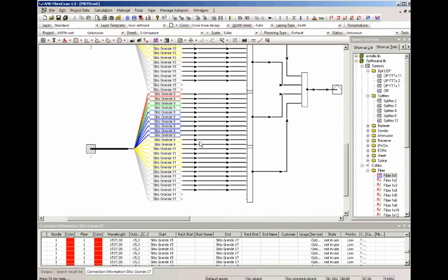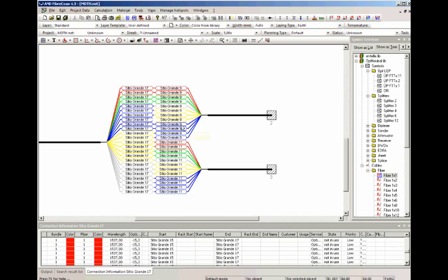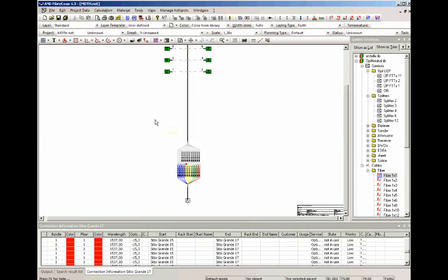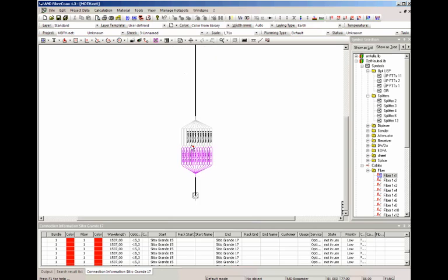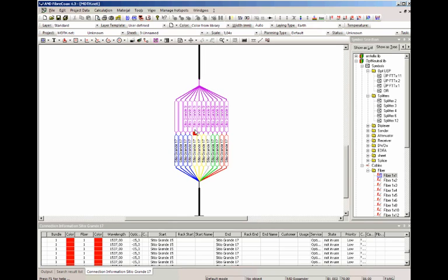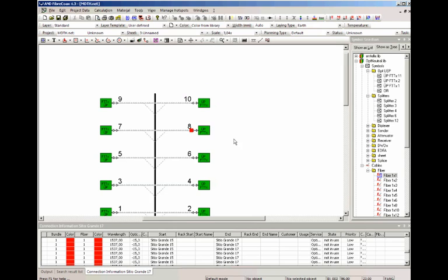If you want to quickly jump to a customer, you can just move your mouse on the end of a leaf and press W. You will jump to the next microduct connection on that side, and this means you can jump through to the house, up to the customer.